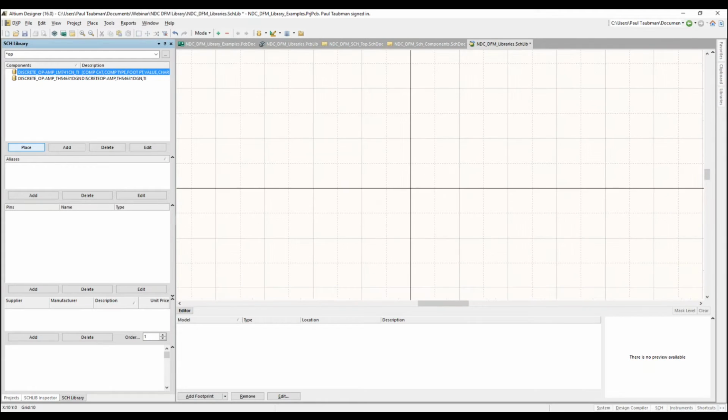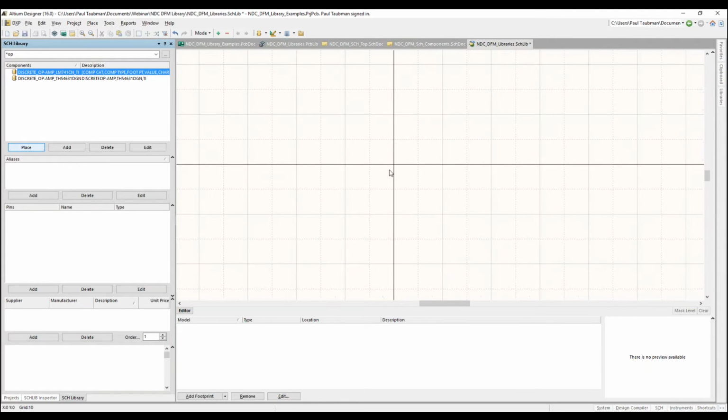And again, I want to do this over here on our center point. Now, as for putting things on the center versus in the top left corner, it depends on how you do it. If your company wants to do everything in the top left corner, you can. That's been the traditional way of most of these. Really, this crosshair is a reference for the cursor. So when you place down the part, it tells Altium, hey, this is the reference point of the component.